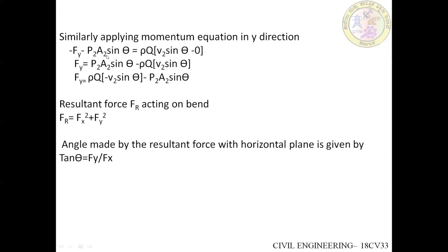Similarly, if you take the forces in the y direction, we will get the force Fy exerted in the y direction. So this is the equation. The resultant force acting on the bend can be calculated as the square root of Fx square plus Fy square, and the angle theta will be equal to tan inverse of Fy by Fx.